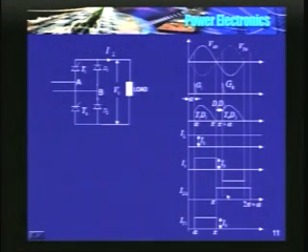So if you see, in one circuit some devices are conducting for a longer duration and some devices conduct for a very short duration. The magnitude of current flowing through each device is the same. I have assumed the load to be highly inductive, so the load current is constant and ripple free, with magnitude I0.